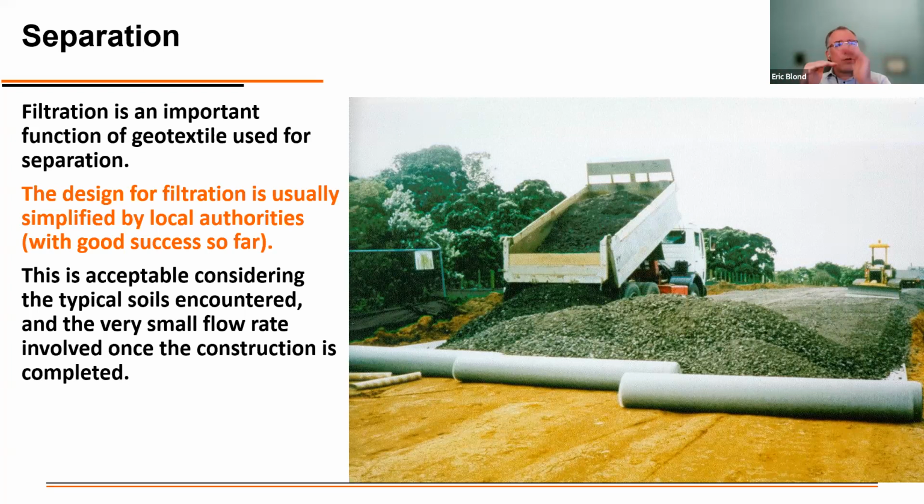If the water is blocked at the level of the geotextile, you will still have water pockets under the fabric during installation of the gravel layer. And you will, in the long run, have water standing on top of the fabric. It is not what we want. But in terms of service, we have minimum quantities of water circulating through the geotextile, and therefore it is not critical. So I want to emphasize on that.